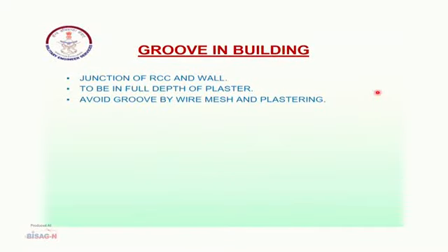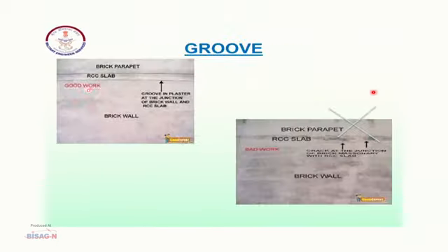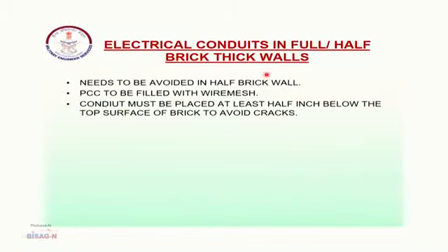Grooves in buildings are very important. You cannot avoid cracks where 2 types of materials, say RCC and wall, are there, but with proper provision of grooves, we can hide these cracks. These are the photographs which show the correct groove and incorrect groove.